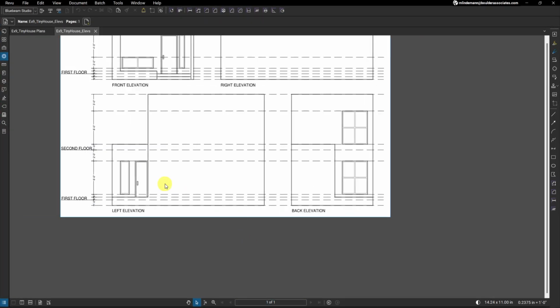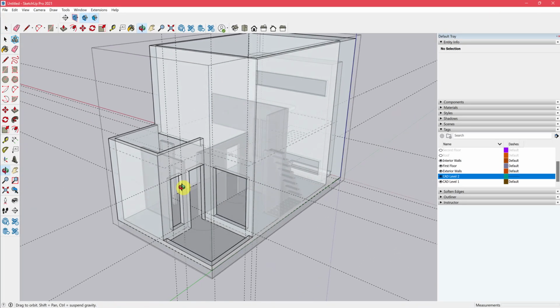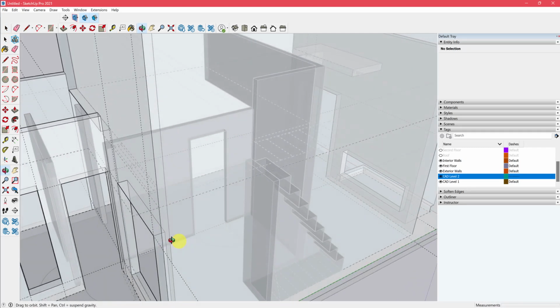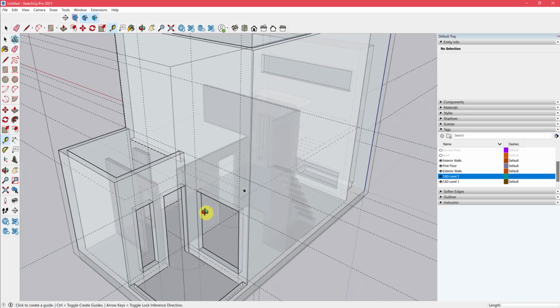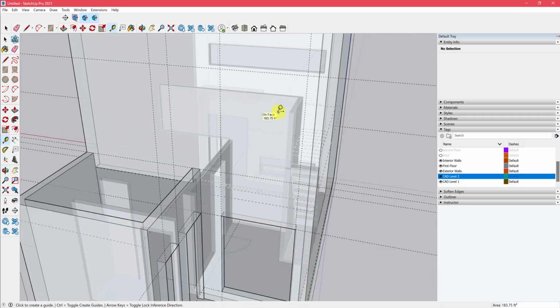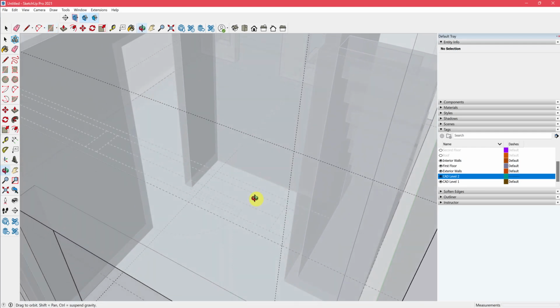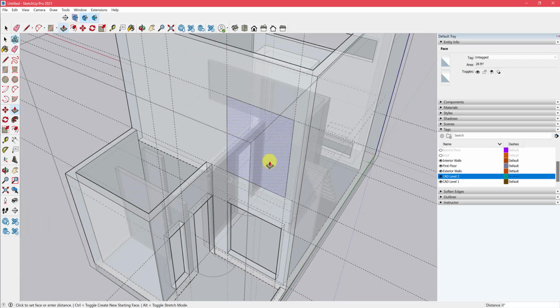And let's check out the height. 1 foot above the second floor, 6 feet tall. Nice. So let's start at my second floor. Can use those AutoCAD lines to determine where that is. Up 1 foot and another 6 feet. Trace over. Make sure you get that intersection. Sometimes it might try to grab something else. And push pull it through.